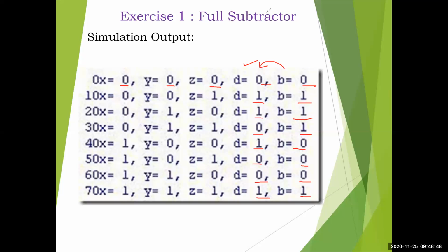You have taken the second operand's complement, then you have added it, and if there is a carry, you have discarded it, or you have added it to the least significant bit. Recall these concepts. So a full subtractor is just to show you, you can design it like any other we have shown, but normally subtraction is not done directly, it is done using addition. That's why it is kept in the exercise, just to have a grip on your operators.